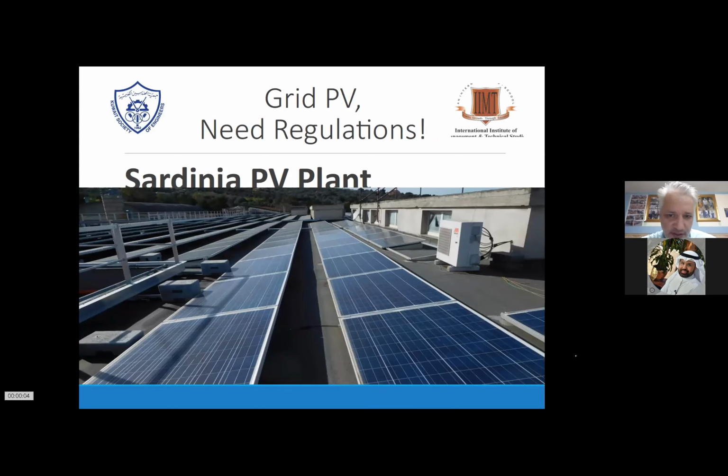We also encountered these problems with the bricks, with the floating device. Also later on, they installed some railings, and that caused, of course, a lot of problems with the shading and underperformance of 10%. So even though the shading looks very small and tiny, that's already 17 to 30% of the module's performance, because it's affecting several substrings.